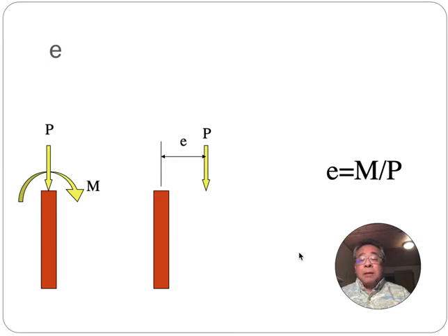And we'll talk about this a lot. We'll talk about the eccentricity of the load on the column. Now, the load isn't physically offset. What it is, there's an axial load and a moment, and that's equivalent to putting that axial load offset on the column. And the way the numbers work out, it could be like this. It could appear to be off of the column even.